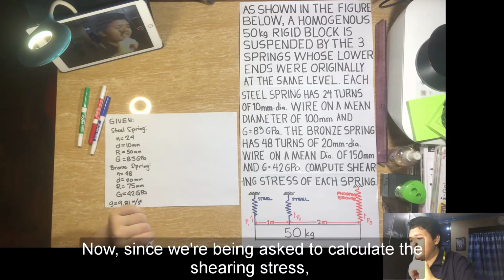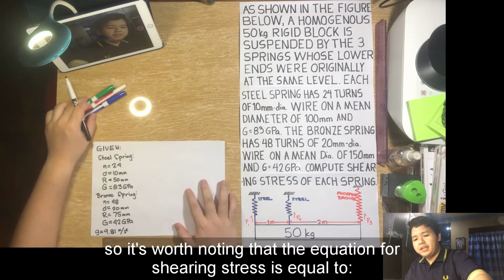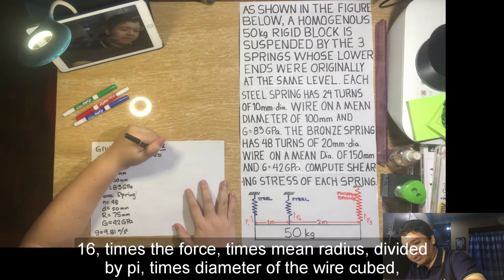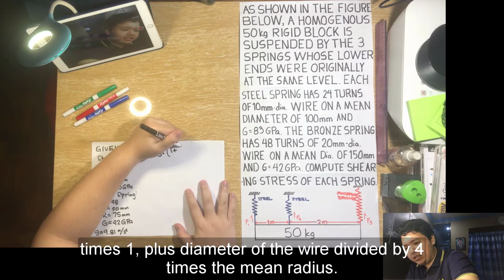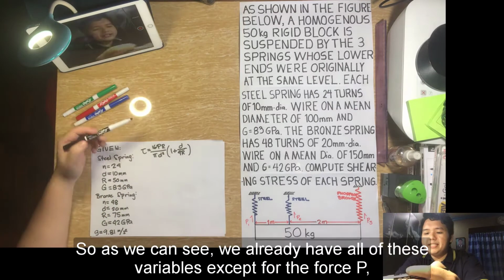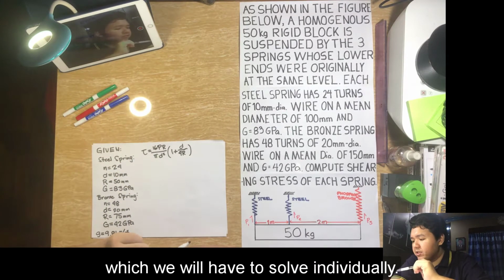Now, since we're being asked to calculate the shearing stress, it's worth noting that the equation for shearing stress is equal to 16 times the force times mean radius divided by pi times diameter of the wire cubed, times 1 plus diameter of the wire divided by 4 times the mean radius. As we can see, we already have all of these variables except for the force P, which we will have to solve individually.